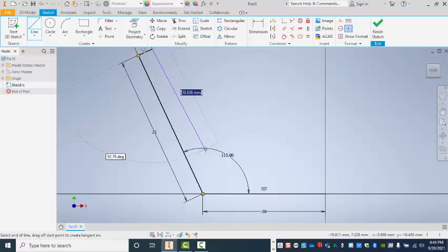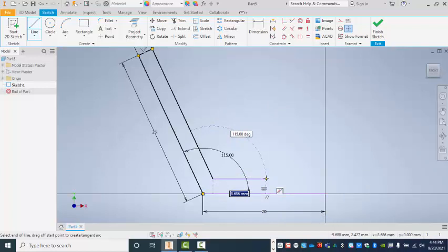And then moving on down here, this is where things might get a little bit different. We're first going to come all the way down, and I'm just going to click right about here. But when I click, I also want to make sure once again that that little perpendicular symbol is showing up somewhere on my screen. So I'll click, and now I'm going to go over to the right 15. So I want to type in a 15 and hit enter.